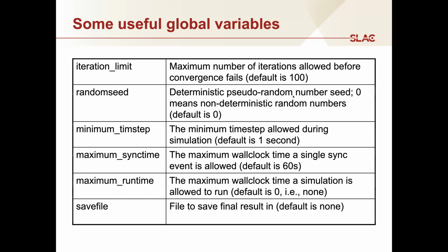Every object has its own random number generator, which is seeded. The seed is determined by an entropy source on your system, so every run will be different. If you want to disable that, you can set the random number seed to some specific number and cause it to follow a deterministic sequence of random numbers, so that given that seed, the simulation will always repeat the same random number sequence, and you get the same result every time.